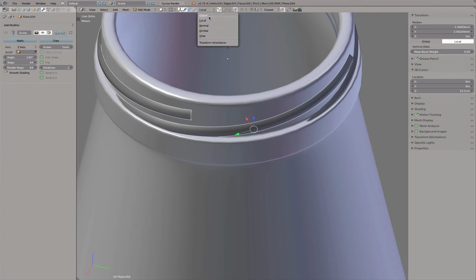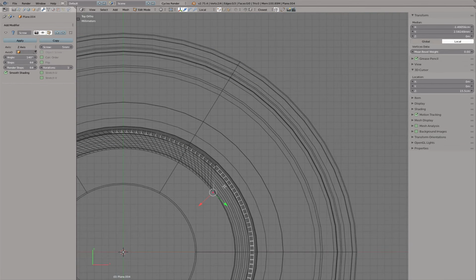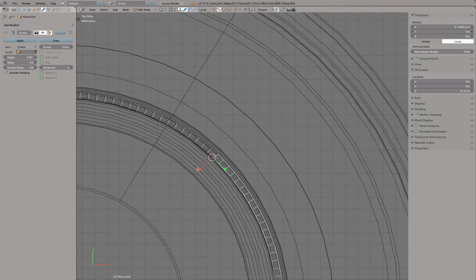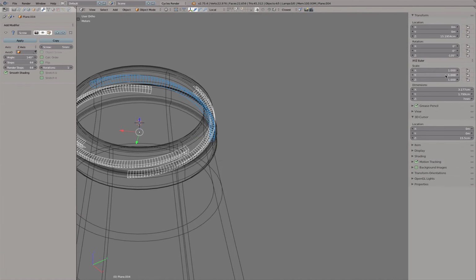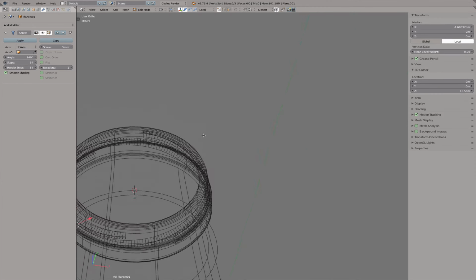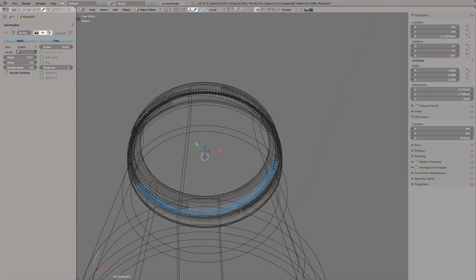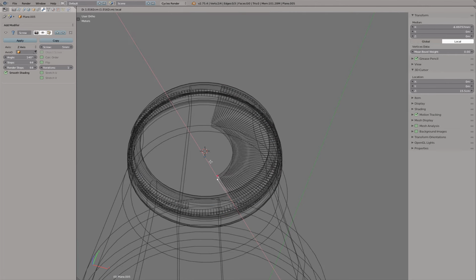Take a look at how, for example, the axes for the X, Y, and Z manipulation change when I switch between global and local. So let's go into top view, Control Z, undo, and there you see now I can move these 2 points along the x-axis perfectly towards the object center, because I also had the object rotated a little bit 135 degree. See, when I go to this one, it faces to its unique orientation.